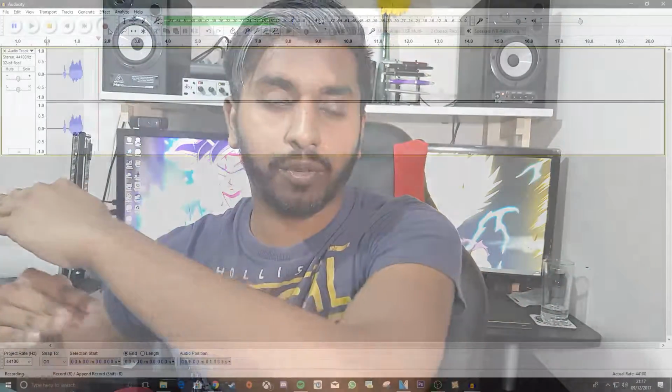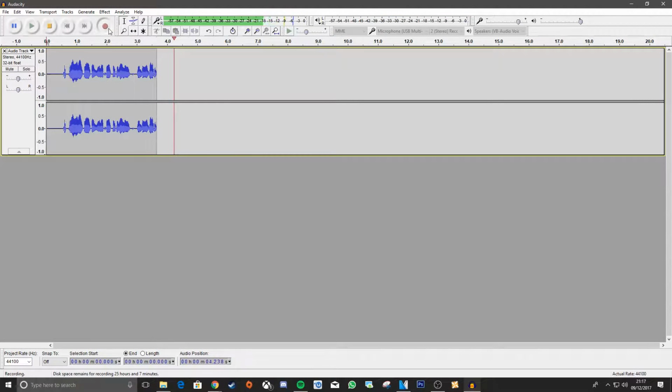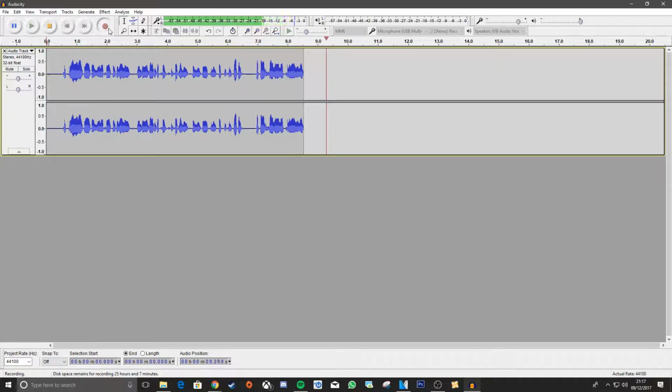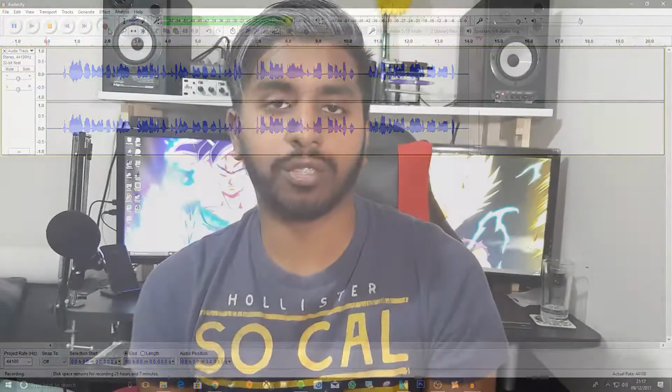The other thing it does, which I really enjoy and I think it's good for, is the louder attenuation or the louder waves you get. If you shout, for example, if you scream, if you get scared, or if you're just speaking too loud, the compressor will not let the audio spike up, basically. It will keep the attenuation at a nice level throughout, and good compressors will do this very well. And again, it's one of those things that for a compressor, you get what you pay for. If you're going to cheap out on a compressor, it's not going to do a good job of it.